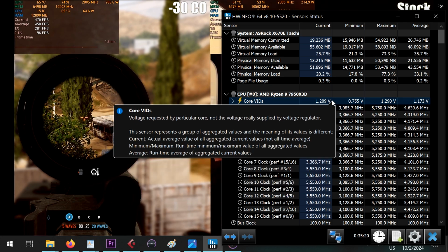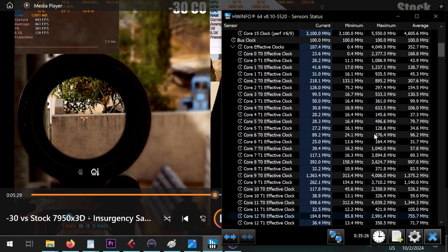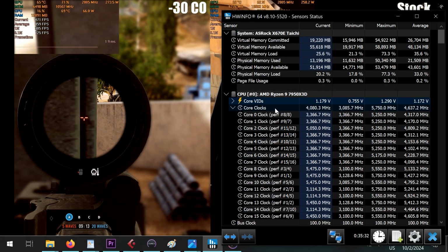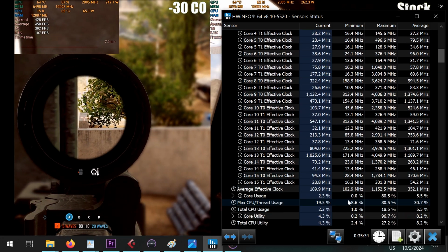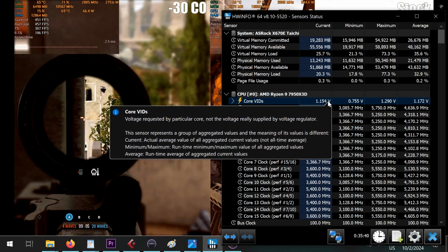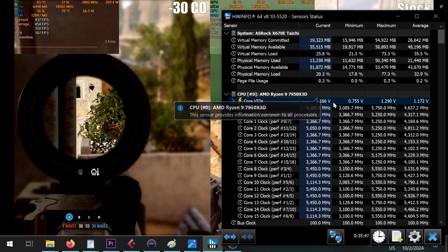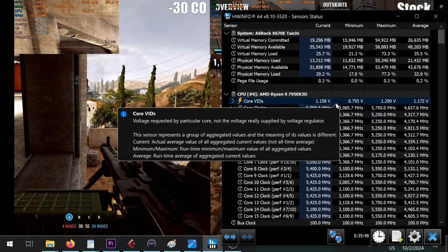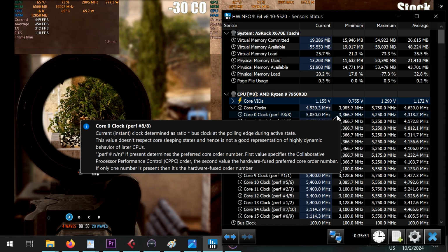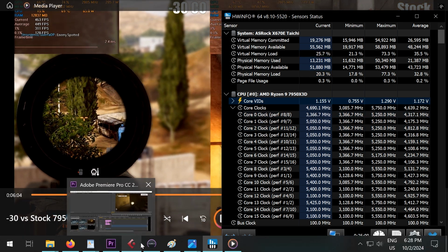This is actually good. You want your CPU to go down, because in this case for the AMD, your CPU is basically resting. It's not doing anything. It can draw less watts, and that's the goal. But on Intel, I had like 1.335 as the highest core VID, and I had like 1.32 to 1.28 range at all times, and that's amazing. That's what you're supposed to have, and that's why when I showed you Intel, it was like that flat line almost.